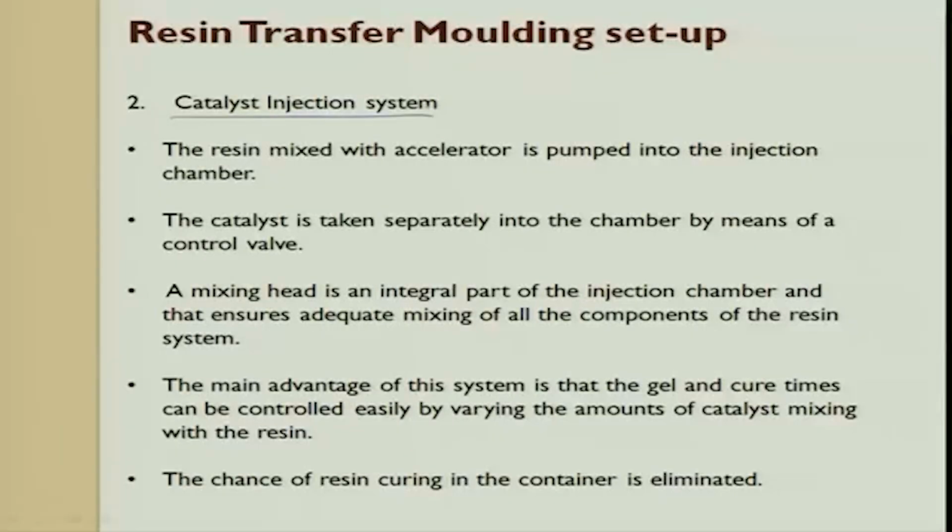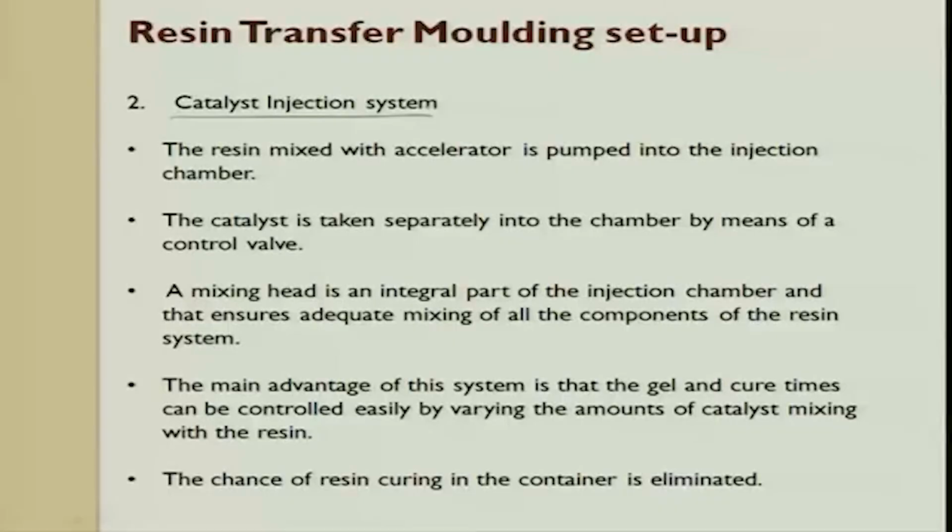Until and unless you mix this catalyst or hardener, the reaction does not happen. So, to a large extent you can control the curing cycle. The catalyst is taken separately into the chamber by means of a control valve. The mixing head is an integral part of the injection chamber and ensures adequate mixing of the components. So, this is the other one. Catalyst is injected separately.